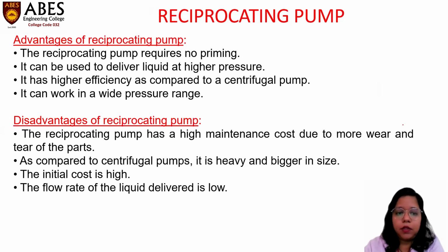Disadvantages are that it has a higher maintenance cost due to more wear and tear of the parts. As compared to the centrifugal pump, it is heavy and bigger in size. The initial cost of these pumps is very high. The flow rate of the liquid delivered is low.